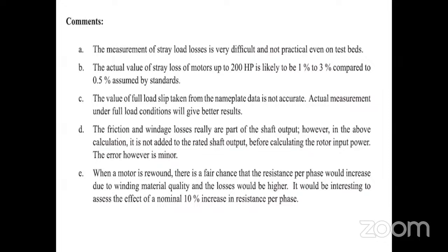The third point is the value of full load slip taken from the nameplate data is not accurate. Actual measurement under full load condition will give us better results. So stroboscopic measurement will give us the actual speed, sir.